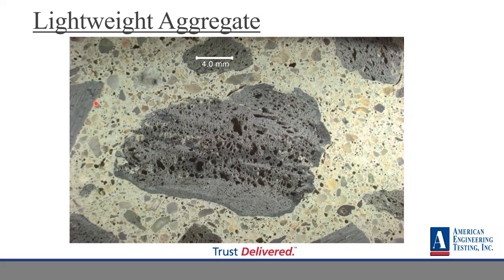It creates a glassy texture in it. The reason people make lightweight aggregate and use it, they typically use it in building structures because it can reduce the dead loads from floor to floor on high-rise buildings, and can produce a lot of savings in building foundation and other reinforcement. So it is pretty neat engineering.